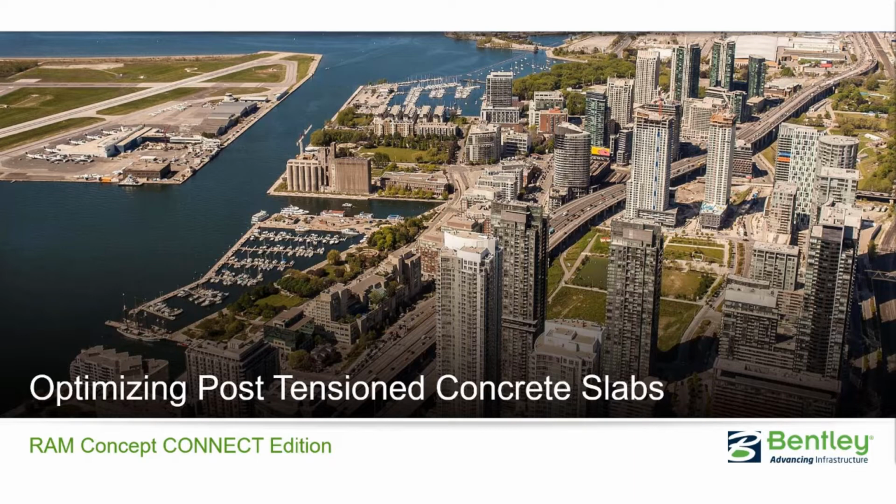Before we begin our optimization workflow, let's first discuss the traditional design process for post-tensioned concrete slabs and some of the advantages you can expect by utilizing an optimization workflow instead. Traditionally, post-tensioned concrete slabs are designed by manually defining a post-tensioning solution that satisfies the minimum pre-compression and maximum spacing requirements. You would then add strands until the flexural tension stress limits are satisfied.